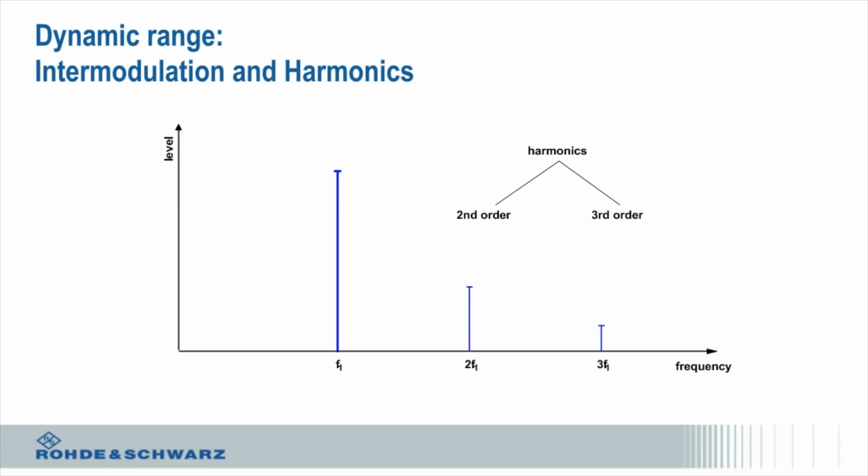So when you're looking at the dynamic range of a receiver, this is really everything coming together. I'm saying I want to know what's the smallest signal I can receive. This again could be my cell phone. What's the smallest signal I can receive? I'm far away from the base station and I can't really hear it very well, so it's a very small signal. I'm worried about the noise figure of my front end, to a very big signal where I'm close to the base station and it's really big, and I'm going to get these intermod terms or perhaps even harmonic terms. So when you design a system, you're looking at the dynamic range, i.e. the very smallest signal all the way to the biggest signal.